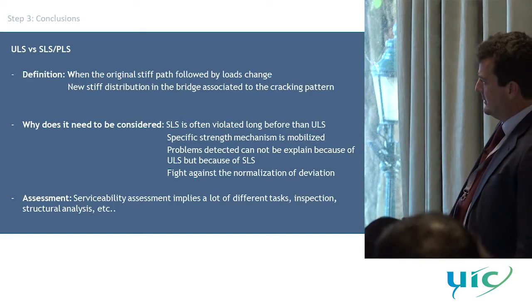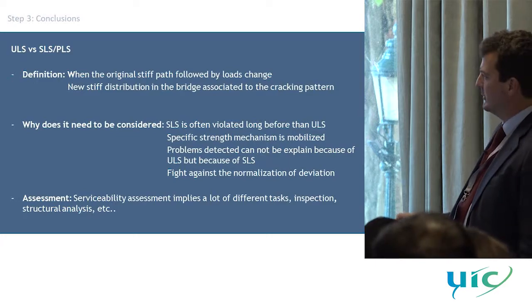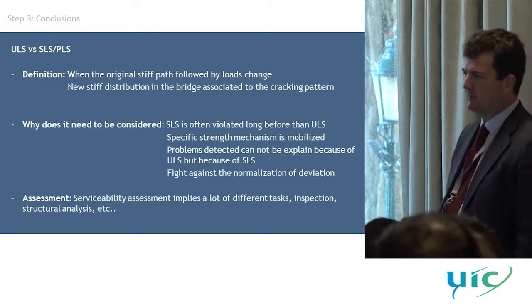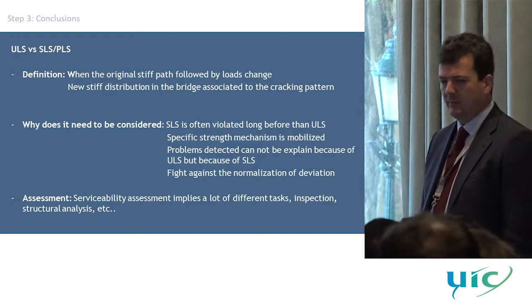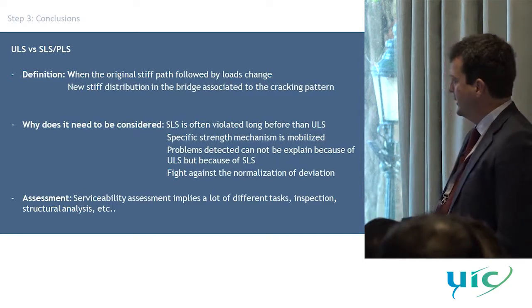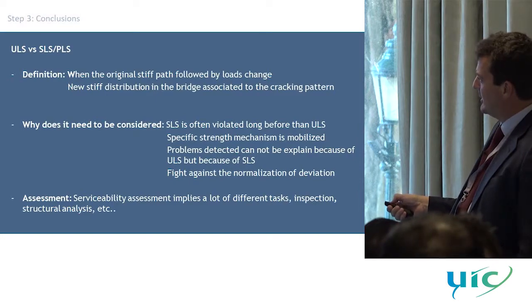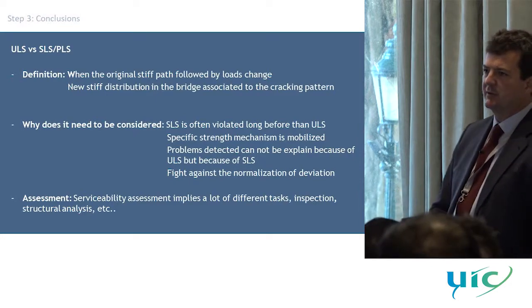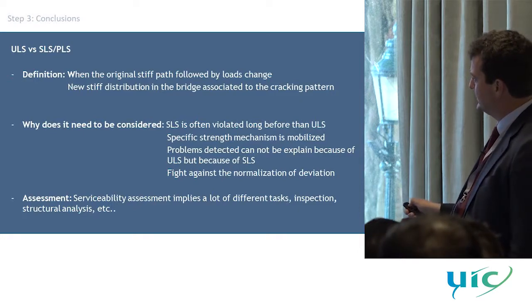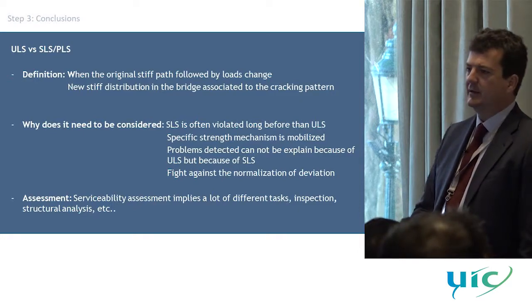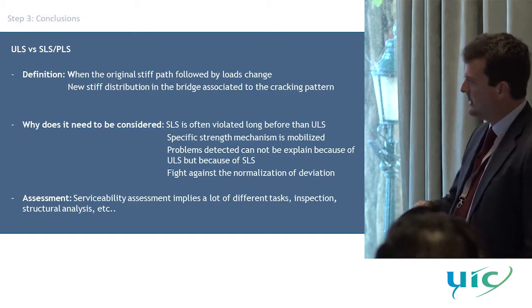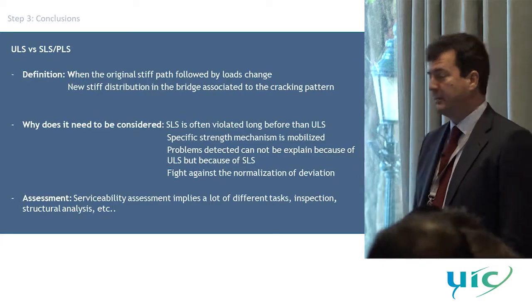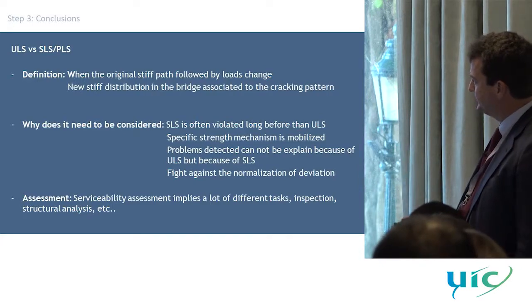And it is true that this service loading, I don't know how to call it, maybe permissible limited state, serviceability limited state, is often violated long before the ultimate limited state. And that's the problem in masonry bridges, that we can have very, very big values for the ultimate limited state, but we are not accomplishing the permissible limited state. And this distance, as Matthew has already said, changes a lot depending on the bridge, depending on the construction details, depending on if they have internal spandrels, depending on everything.